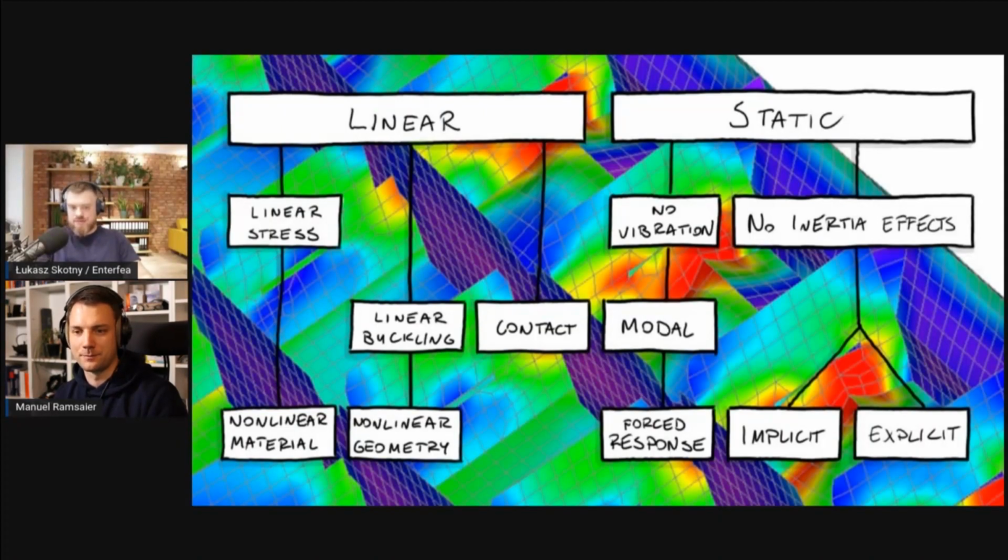But harder convergence. So it's a better result, but it's also harder to achieve, which is somewhat fair. Yes, absolutely. If we would like to compare, linear analysis of a big model will take 5 minutes. Computing with nonlinear geometry and nonlinear material will take you 2 hours. So it's not for free. There is a cost associated with it.